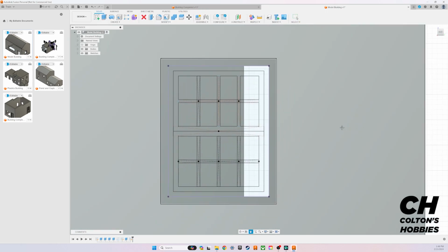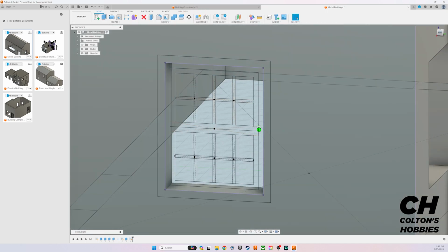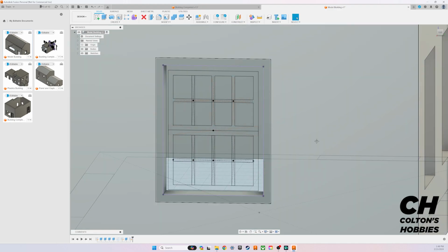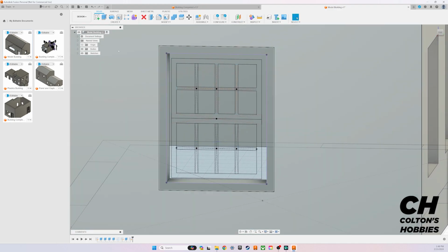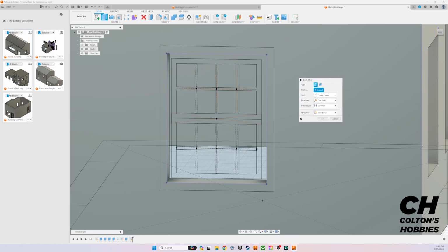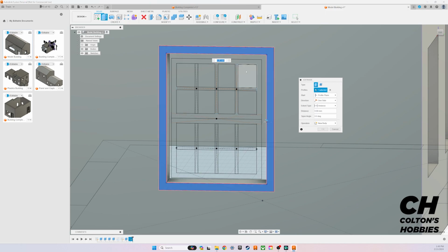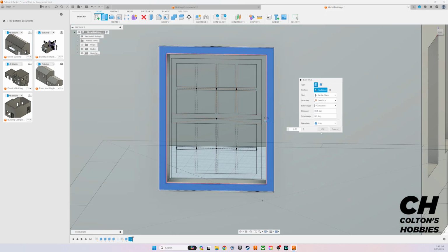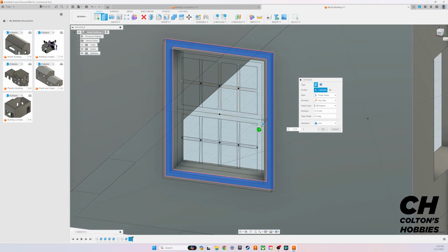And let's start extruding. And as we extrude, I do things in a certain order just to keep myself organized. The operation is going to be really important, and some of these other settings. So let's go through all of this. So we're going to extrude this forward by 0.75. And I know it's forward because it's a positive value, and that's the way that the arrow is pointing.